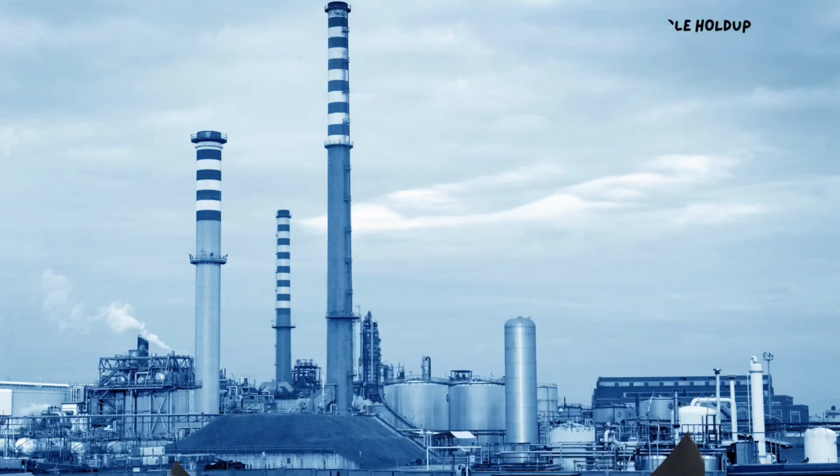throughout the liquid. Holdup refers to the condition where the amount of liquid in the tank changes over time. This happens when the inlet and outlet flow rates are not equal. As the liquid volume changes, it affects the heating rate and the temperature response of the system. Because of this, the process becomes more dynamic and challenging to control.